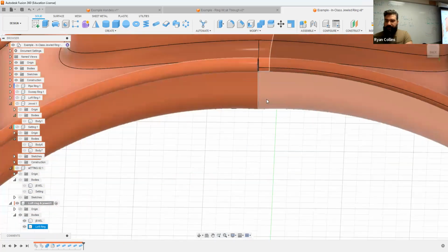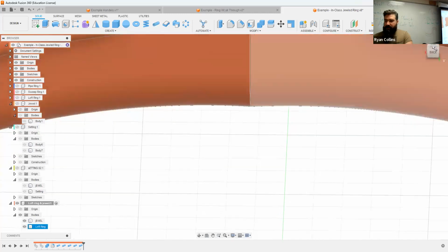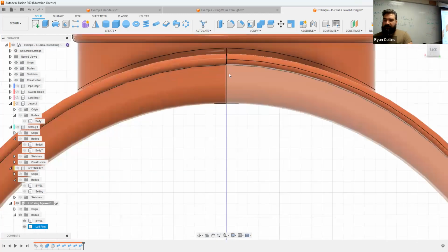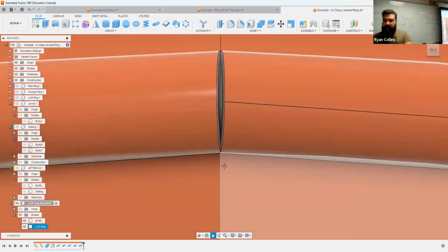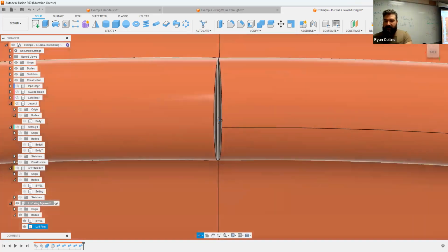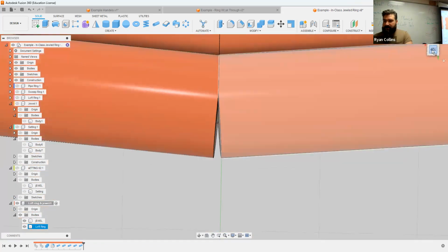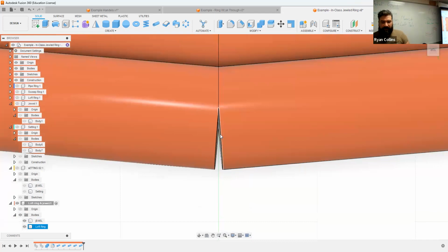Now, I will warn you, because this is an odd edge, look what happened right here. Oops, geez. At the very top here, it created this little cavity. And that is because the pipe tool is merging at an angle. Remember that the pipe tool ends perpendicular to that line. So the way you'd have to fix this would probably be to extend something between there.